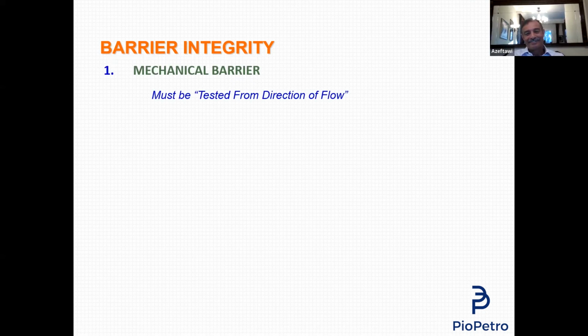So please test it from the direction of flow. Everything we design is for a certain purpose. We designed the valve to be used fully open or fully closed.